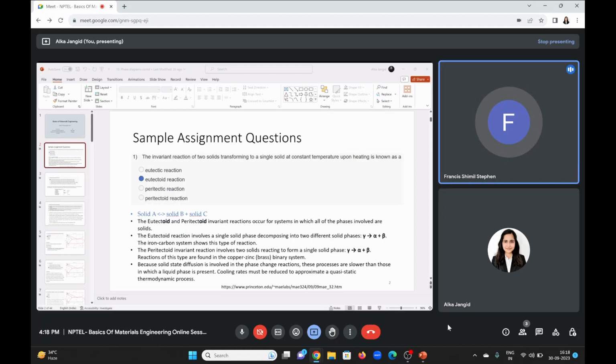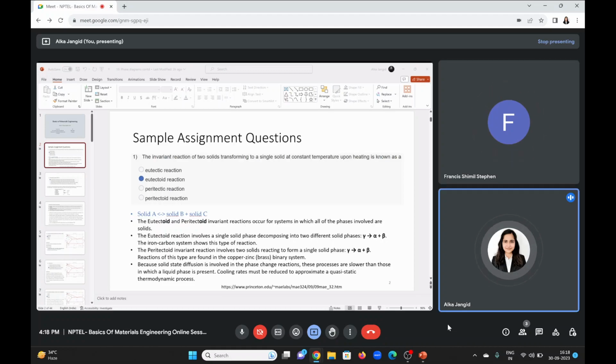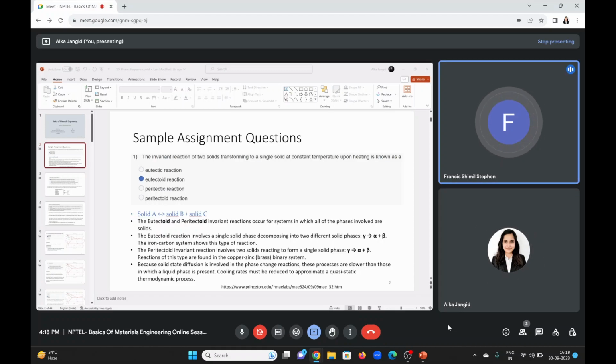Ma'am, I will read out the thing. What they are saying is during rolling, the slag particles will get elongated in the direction of rolling, which increases the strength. So in wrought iron, you are rolling it, then it is elongating your particles, so it is increasing the strength of the material. Also, they are saying that during the forging or hammering, it is mixing it with the iron.